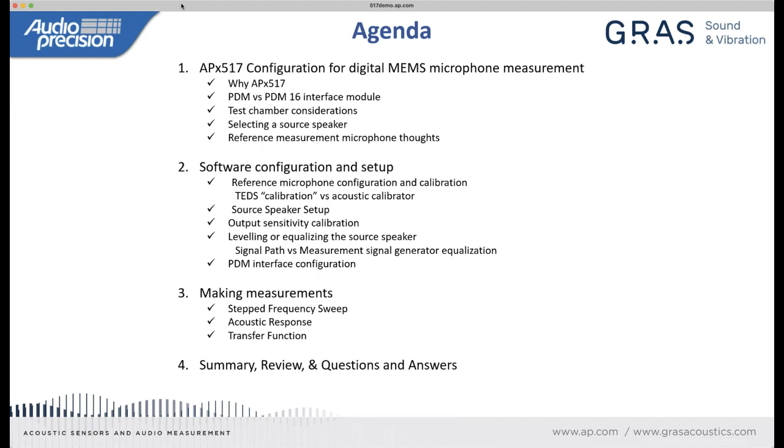But today we'll talk specifically and demonstrate specifically testing a digital MEMS microphone array that has a PDM, or pulse density modulation, output, and doing that using our APx517 analyzer and PDM16 input module, which is a pretty specific and apt solution to this challenge.